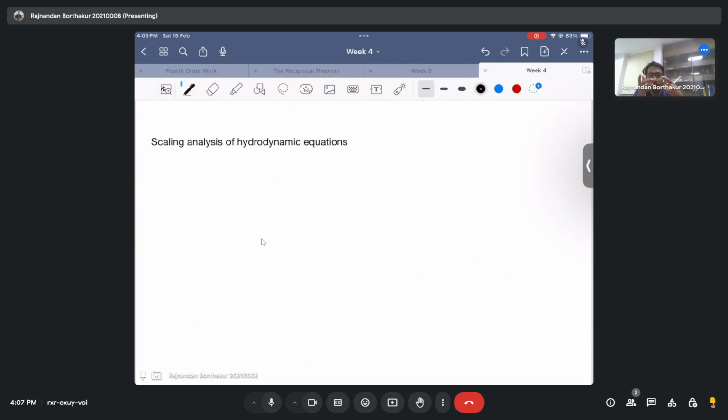So the idea is that if I define certain universal quantities like the Reynolds number, it becomes easier for us to deal with the variations in the problem, rather than changing inherent quantities like density and viscosity, because these quantities are a function of what the fluid is, and then it doesn't become universal. So it becomes customary to define these non-dimensional numbers, and you will see they just pop out of the analysis when you non-dimensionalize the dimensional form of the differential equation.